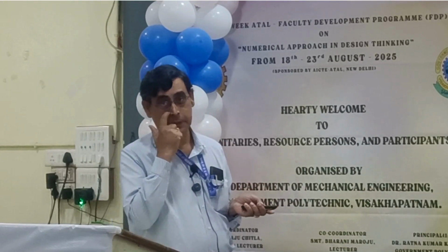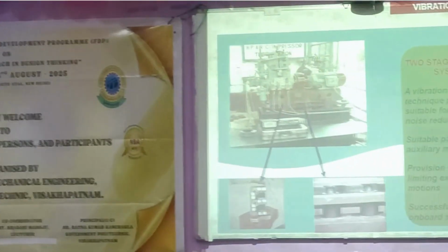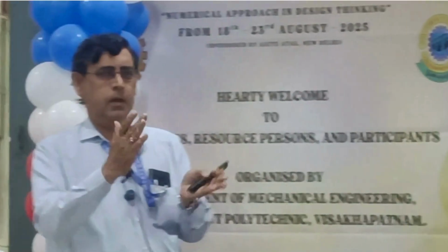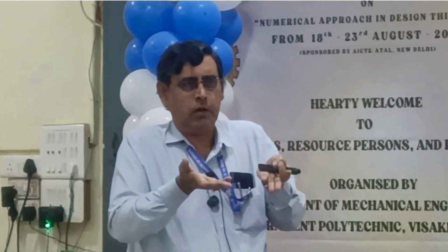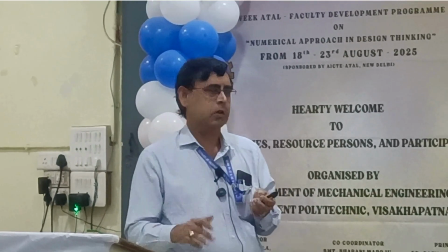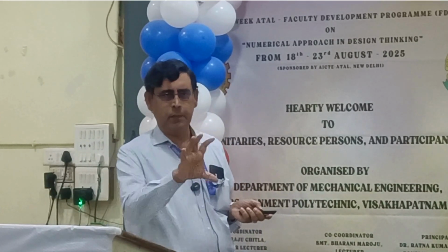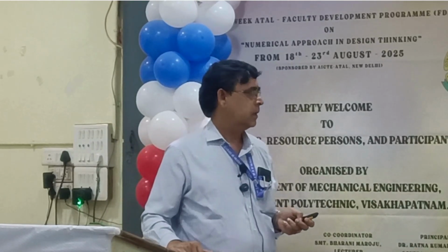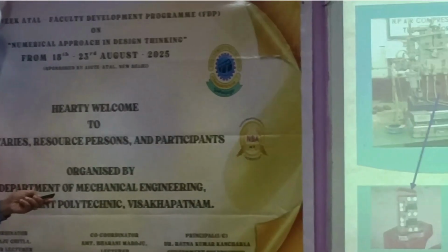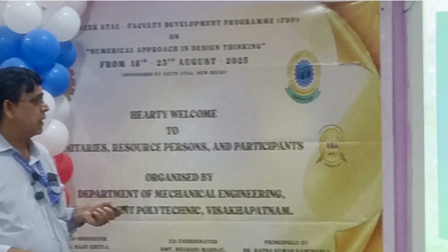So this is one application where we have developed two-stage mounting systems for various shipboard applications. And this is of course a limiter, because whenever you are increasing the height of the base, there is always a tendency of equipment to rock. Because whenever you have height, the CG will be difficult to maintain, right? So therefore it tries to rock. To avoid that, we have a design called limiter design, so that it limits the sideways movement. So the engine will not topple. So that also we have placed here, right? So this is one application.